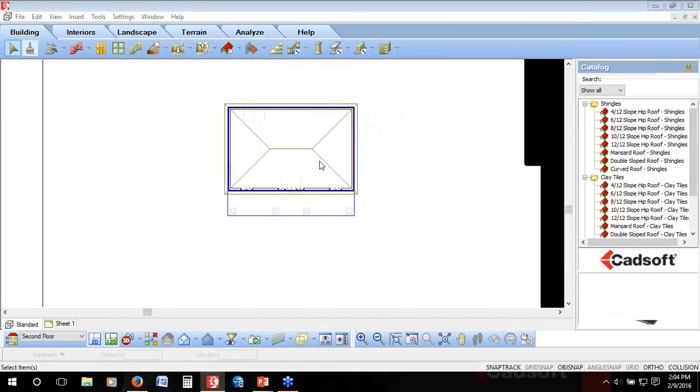There's no way of automatically determining that. That has to be a secondary step. So we allow that to be a secondary step by left-clicking on the overhangs and then clicking on the arrows that appear to choose which sides you want to be a gable later. So that's why you won't find it in the default catalog, because it would be an extra step.